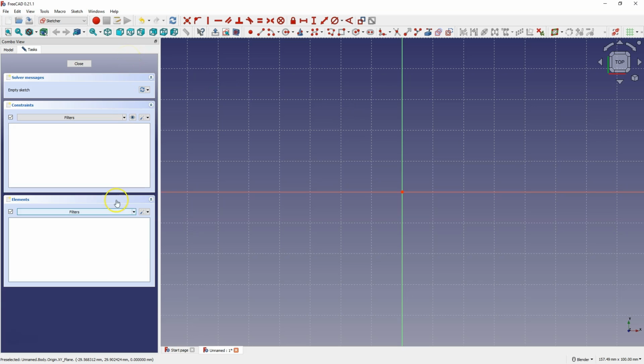This is the Sketcher module, where we create 2D shapes. And here we have tools to create different shapes, and these shapes can be combined with each other, and there can be several different shapes in one drawing. Before we go on to create a sketch, click here and make sure that you have these two options of automatic constraints and remove redundant constraints automatically checked. Okay. Now let's draw a rectangle.